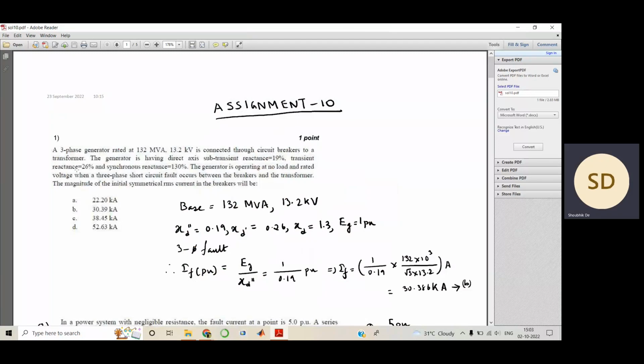So this is question number 1. A three-phase generator rated at 132 MVA, 13.2 kV is connected through circuit breakers to a transformer. The generator is having a direct axis subtransient reactance of 19%, transient reactance of 26%, and synchronous reactance of 130%. The generator is operating at no load and rated voltage when a three-phase short circuit fault occurs between the breakers in the transformer, then what would be the magnitude of the...